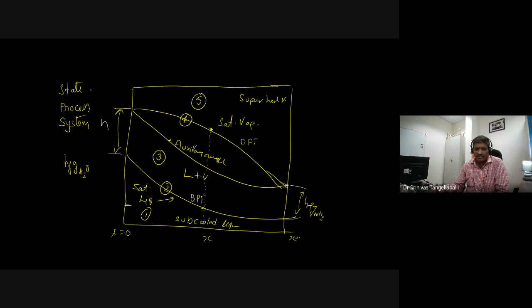This is the ending of the phase change, with the mixture of, let us say for example, x is equal to 0.5. And what about the temperature on this vertical line? The temperature is increasing from the bubble point temperature to the dew point temperature. For the properties, especially the enthalpy, straight away you can take the liquid as well as the vapor. This is completely vapor and this is completely liquid. There is no issue.